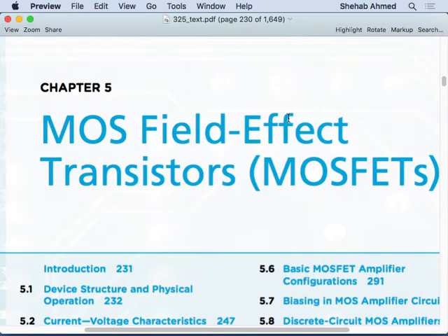It's a very important device, and we're going to build upon what we learned in diodes. We still have to understand that current in semiconductor materials is either going to be due to drift or diffusion. Always the case. In diodes, we realized that diffusion was the main method of current transfer through a device. When the device was on, the current flow was due to the carriers diffusing through the barrier, right? That's when the device was forward biased.